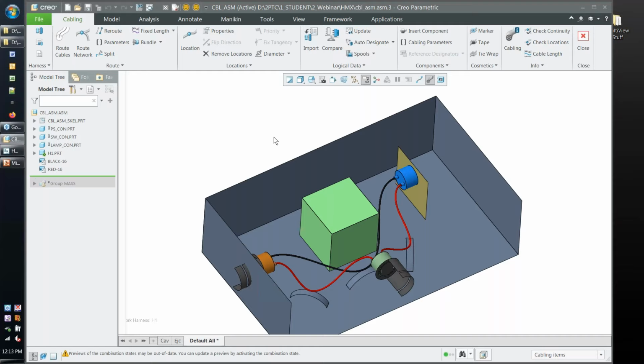where if we utilize Creo, the standard documentation functionality that I began this demonstration with, if we use that type of workflow and we make changes to this assembly, it is parametric to all that stuff, and it updates. So it can cause conflict for people to put out options of harnesses because they just want to be able to reconfigure this assembly, be it the cabling or top level, and then say make a drawing of that. When you use the more conventional techniques, it does become more cumbersome to create the iterations for the documentation as opposed to utilizing the HMX functionality.